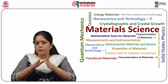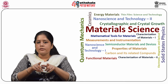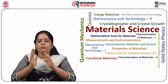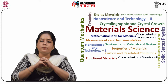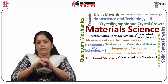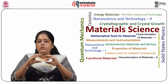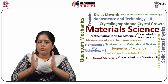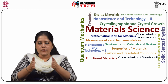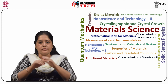Pyroelectricity should not be confused with thermoelectricity, because in the case of pyroelectricity, the whole crystal is changed from one temperature to another, resulting in a temporary voltage across the crystal. Whereas in the case of thermoelectricity, the two ends of the device are subjected to two different temperatures, resulting in a permanent voltage across the device as long as there is a temperature difference.